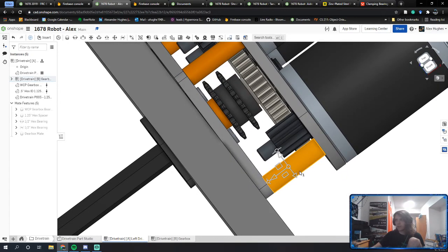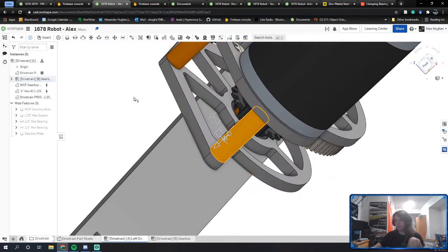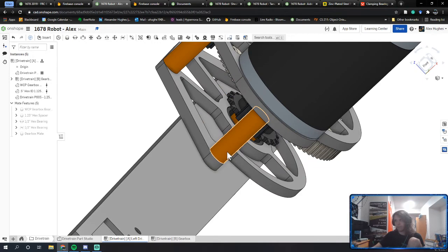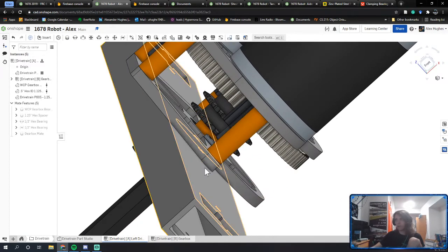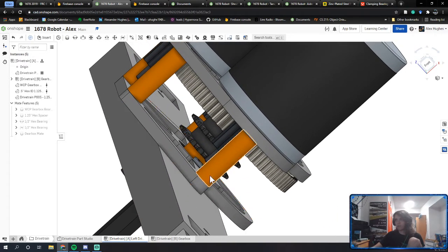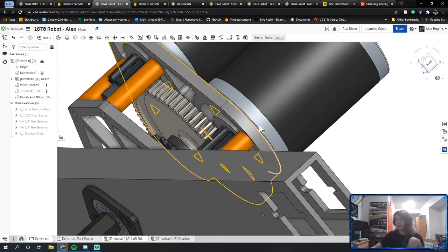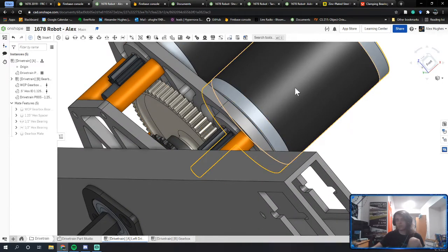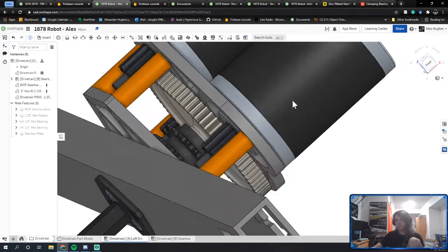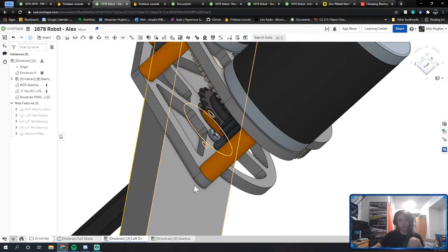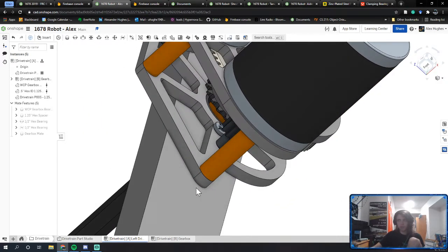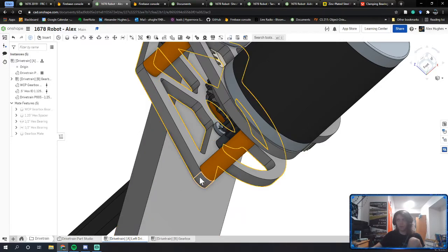But look down here at this little spacer that we have. There's supposed to be a bolt that goes through this hex spacer and anchors into this sim motor, or mini sim. But where would the head of that bolt go? It's going straight into the drive rail.